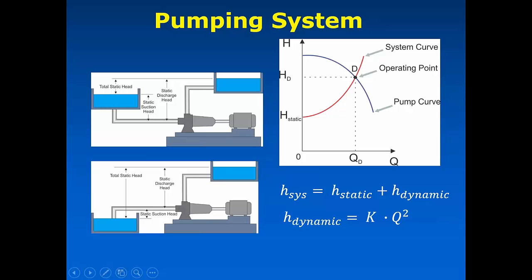So now, just a quick summary of the terminology that I'm going to use today. Here's what the pump curve is going to look like in blue here. So this is flow on this axis and head on this axis. And we can see here that for a given pump of a specific design, we can know what this particular curve is going to look like. That's a lot of information you can typically acquire from vendors and so on. And that pump curve defines how much head you can push for a given flow rate.